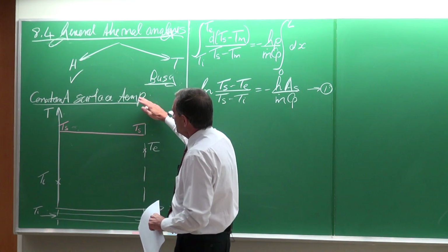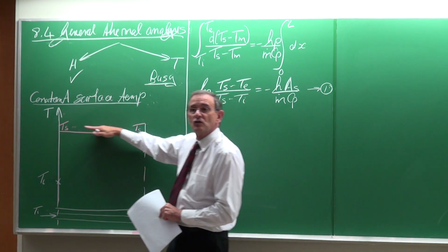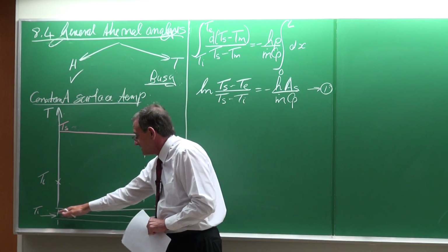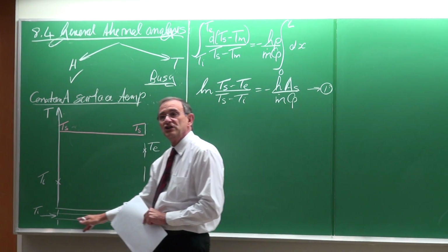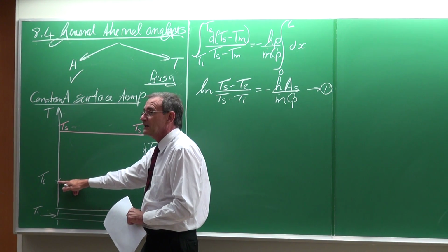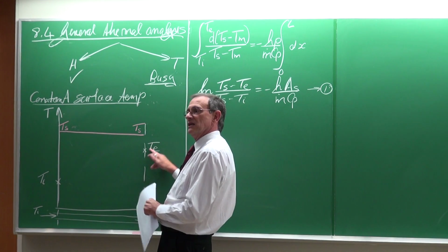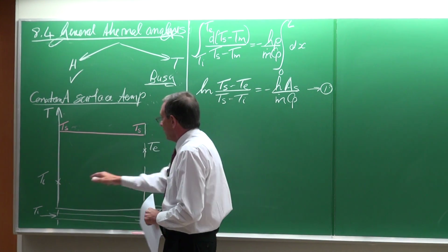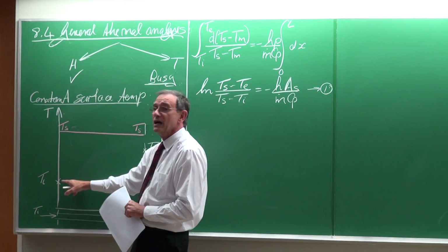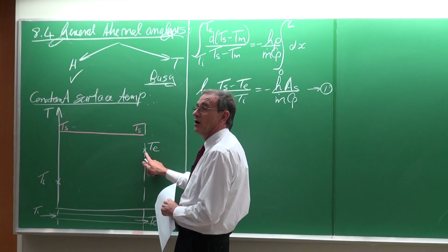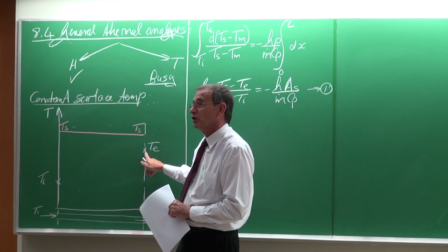So with the constant surface temperature, that is the surface temperature. In this case, this fluid is being heated. The temperature of the wall is constant. If that's the inlet temperature, then we know that the outlet temperature must obviously be increased because there's heat transfer. However, this path is unknown. With a constant heat flux case, it's a linear line. For this case, it is not linear.